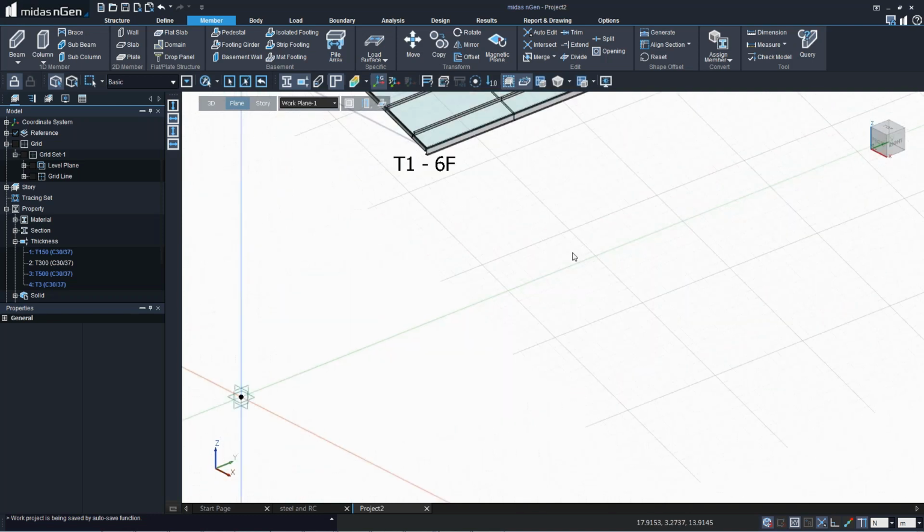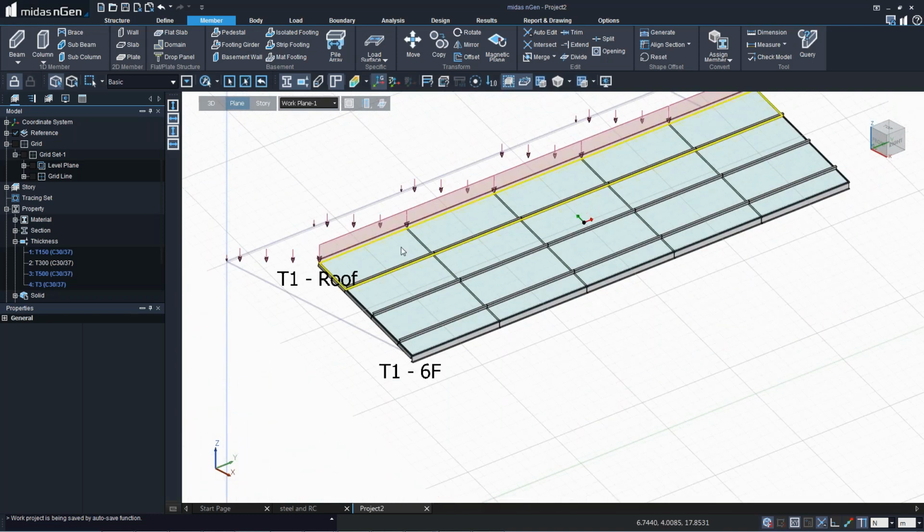Okay, so this is how I have assigned the roofing, and this also I can apply it. I can assign a proper material property to it, and it can be utilized for the analysis purpose as well. But if you want to make it only to assign the loads on these particular elements, then all we have to do is basically connect them to these elements on which the load is to be applied.